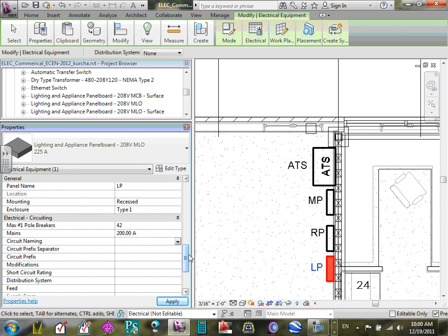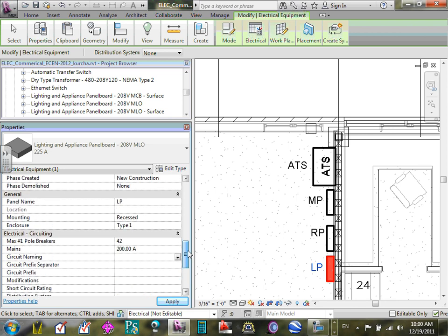The second very important thing, guys, so these are important. I want to remind you, Ashley, it's a NEMA type 1. If you need NEMA 3R outside, this is not your baby. Well, it works, but if you want to pull information about the project and you put NEMA 1 and NEMA 3Rs outside, you might have to go a different family. So this is what it should be, indoor. Okay, 200 amp.